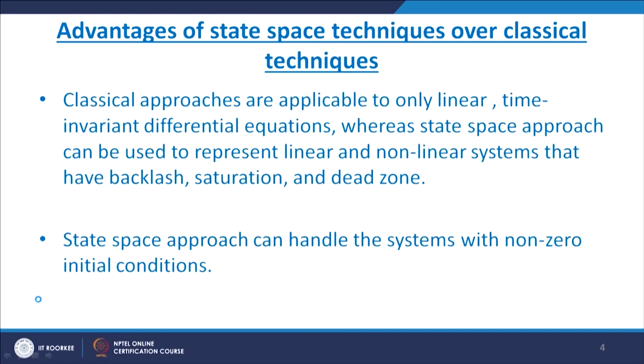Now about the advantages of state space techniques over classical techniques. Classical approaches are applicable to only linear, time invariant differential equations, whereas state space approach can be used to represent linear and non-linear systems that have backlash, saturations and dead zone. Now you will find that in case of classical approach, we are using a linear system only. So original system, and we know that practical systems are non-linear, but analysis using classical approach cannot be possible for a non-linear system. Therefore we have to use the linear model.